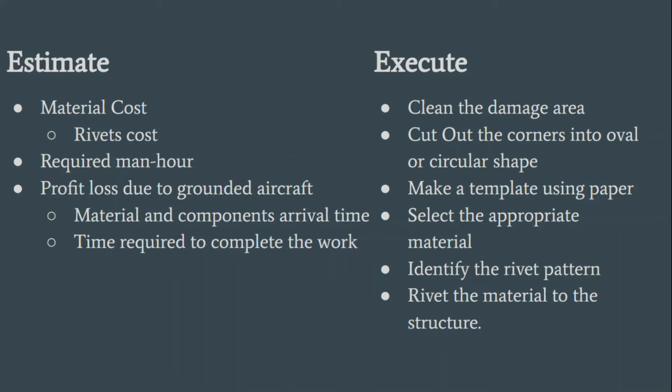To execute, clean the damage area, cut out the corners into oval or circular shape, make a template using paper, select the appropriate material, identify the rivet pattern and rivet the material to the structure.